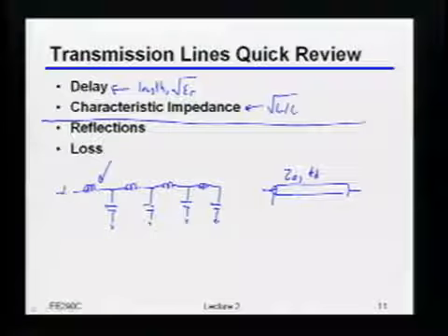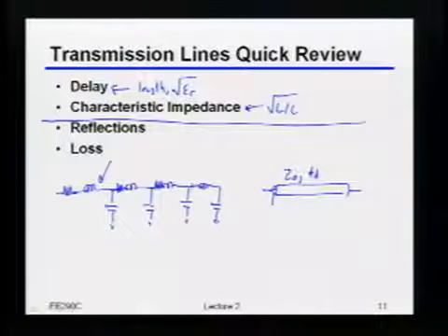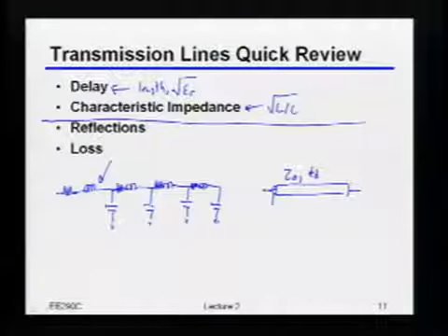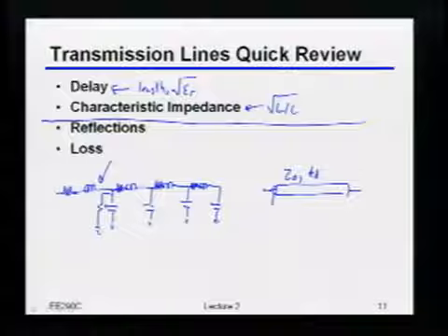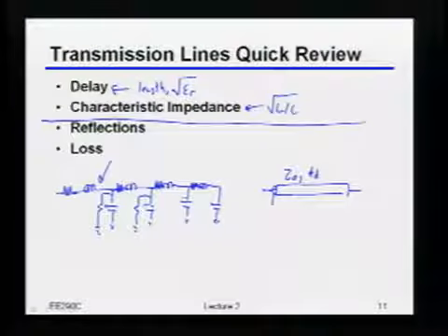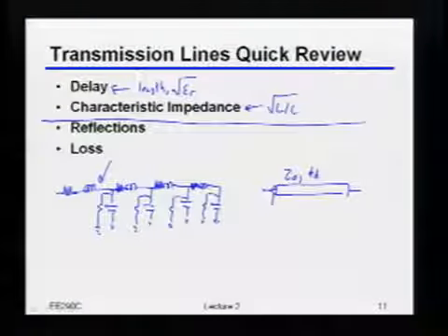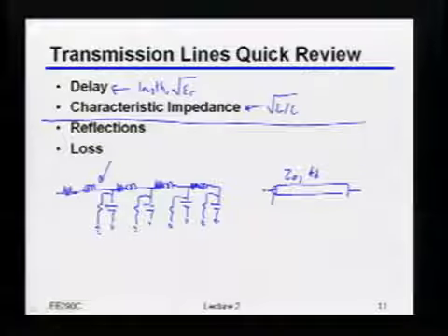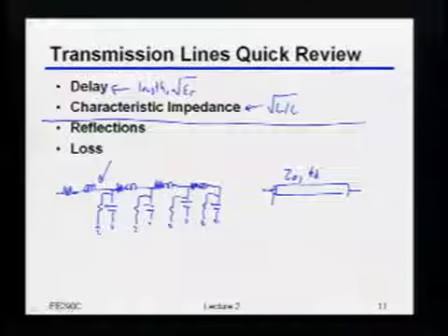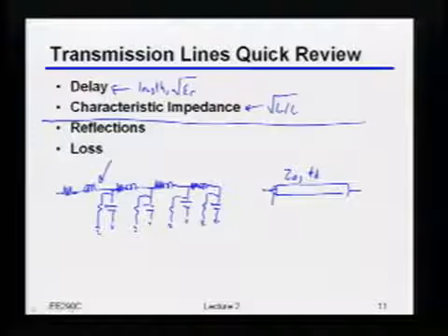So unfortunately, every one of those inductors has a resistor in series with it. And not only that, as we'll see in a second, any capacitor also ends up having some effective parallel conductance. Again, we'll see physically where that comes from in a second. And by the way, those conductances and resistances depend on frequency, so they make life a little bit more fun, so to speak.